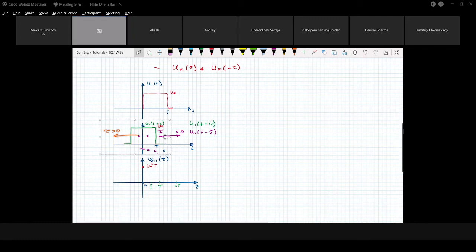And then if I move further by, let's say, T, shift by T, what will be the result of correlation? 0, because simply speaking, they do not overlap each other. So now we can show these points. We have u0 squared t over 2, and we have 0. And of course, you see that the correlation linearly decreases when we increase delay.